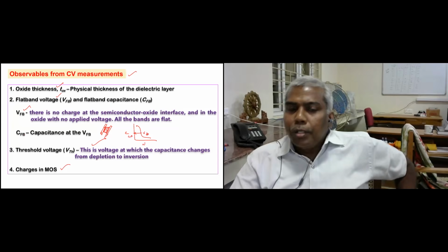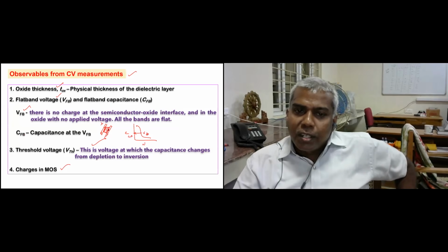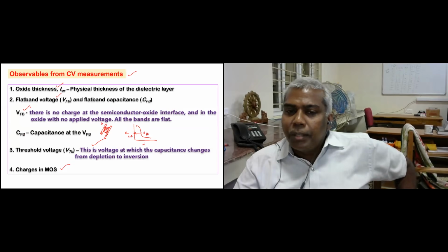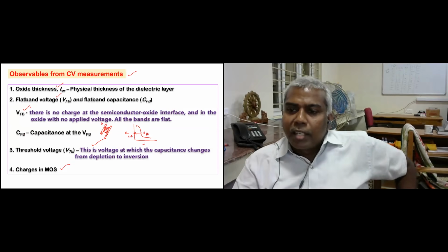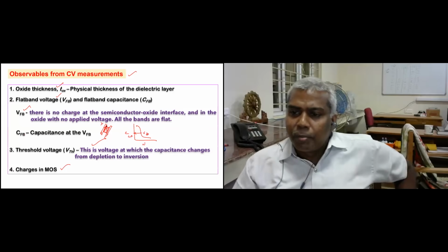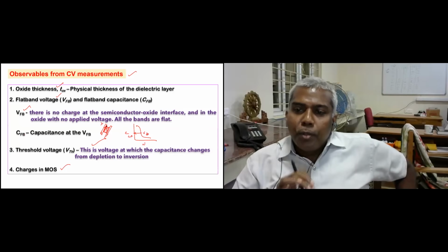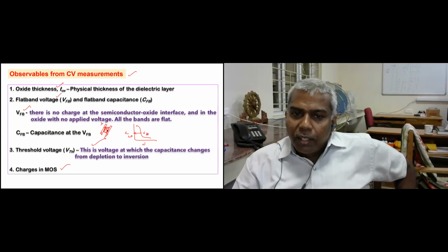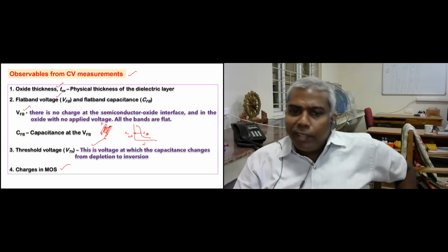dielectric. When you apply temperature, obviously the conductivity of the layer will be increasing, because it is also behaving in a semiconductor nature. We do not want that. We want the dielectric to be perfectly an insulating material. We do not want that to be conducting. If you increase the temperature, exactly the same thing that happens in the semiconductor will happen here.